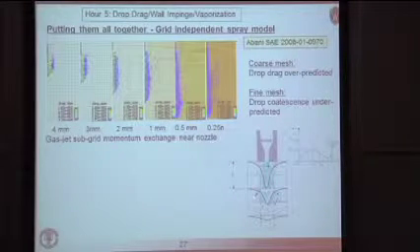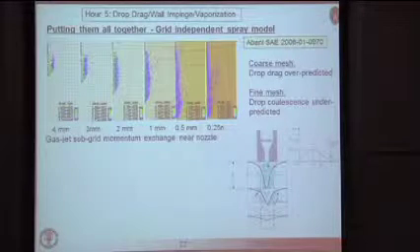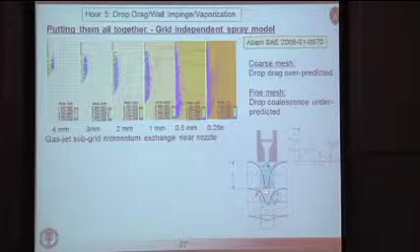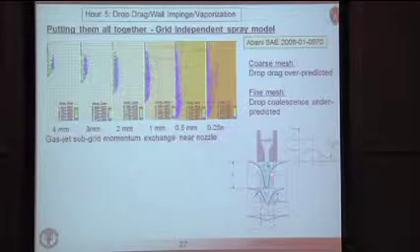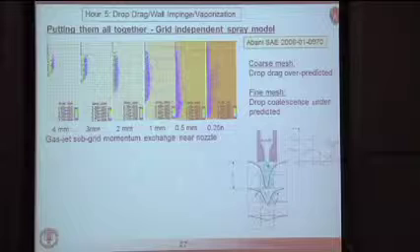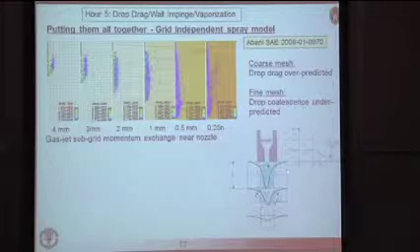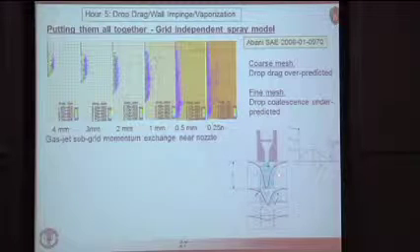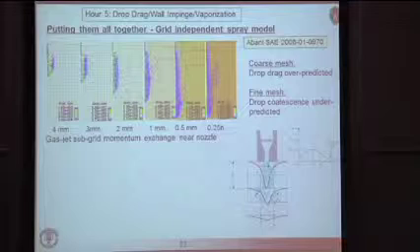see what the velocities would be. Notice the cell sizes are huge here, but now we're talking about a sub-grid scale effect. So we can essentially, for each droplet in this big cell here, look at what the gas jet theory would predict for the gas velocity in that cell. And instead of using the average velocity for just this computational cell, we'll use what the gas jet theory predicts.